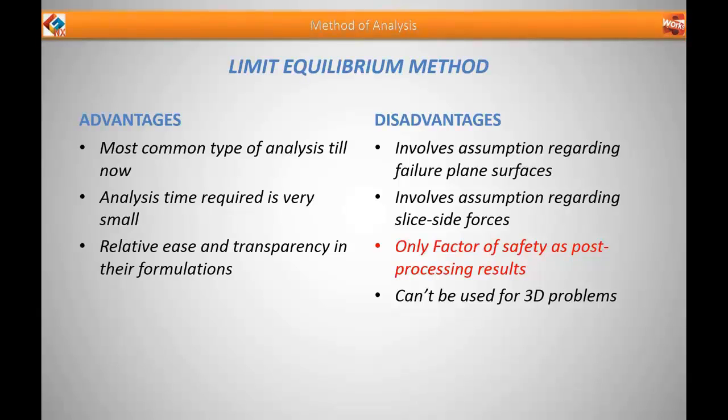The disadvantage of this method is that it involves a lot of assumptions regarding the failure plane surfaces and the slice side forces. And also in the post-processing results, the only thing you obtain is the factor of safety, and it can't be used for 3D problems.